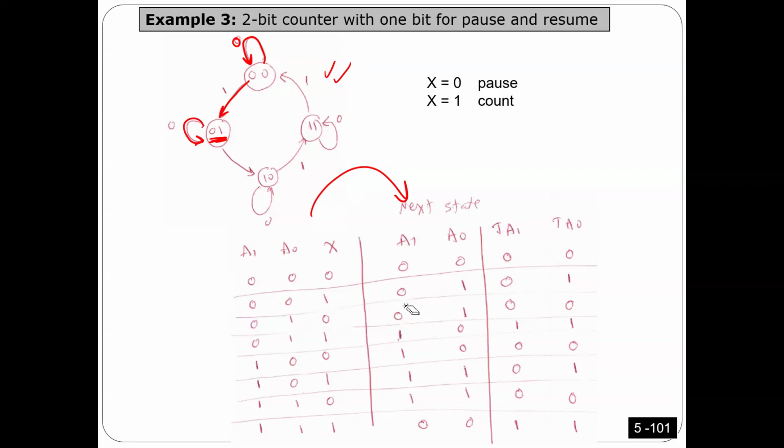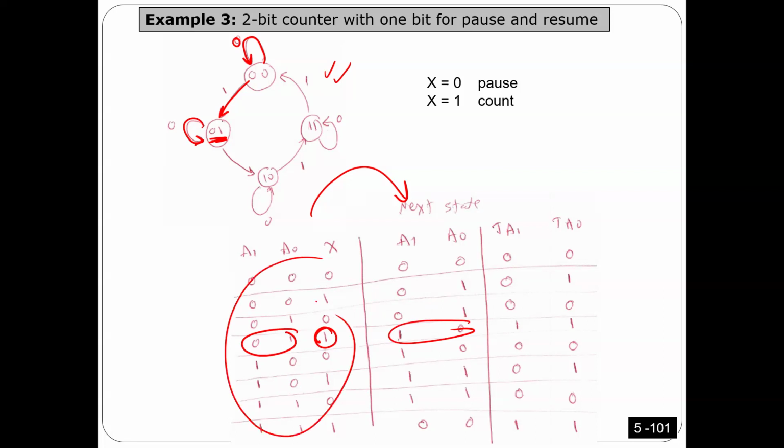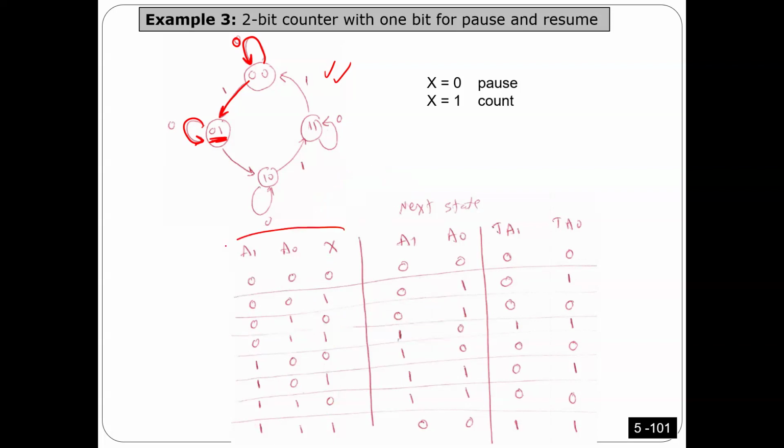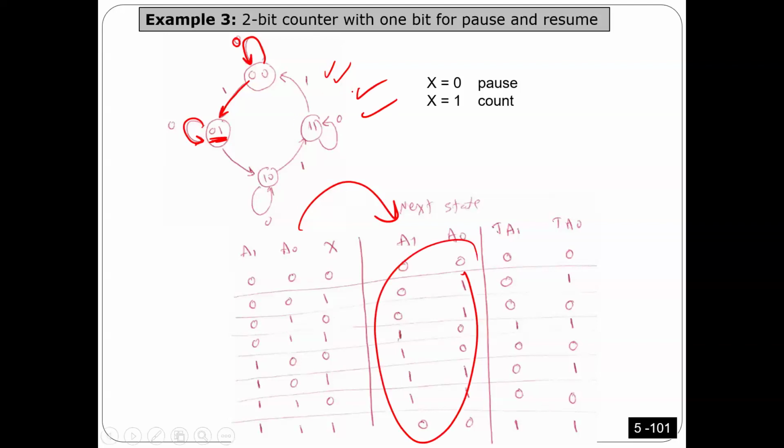Anyway, so also here you can see if it is 0, 1, but x is 1, next time you have to move to 1, 1, 0, and so on. Okay. So again, this is step number 1: you have to put the state and input here, and then write all possible cases. Number 2, to calculate this part here, you actually need the state diagram.